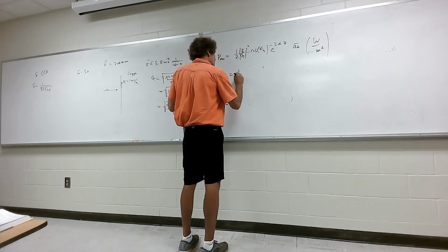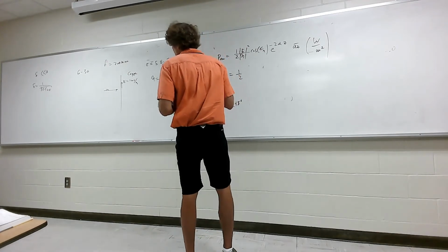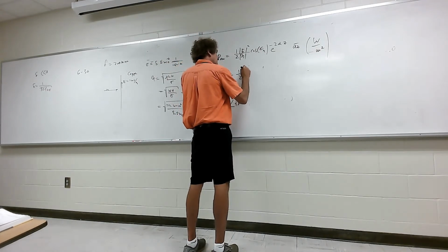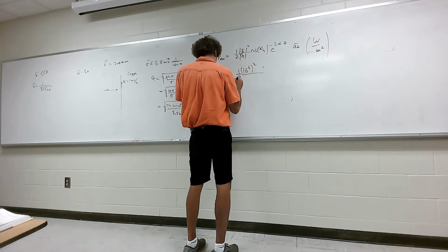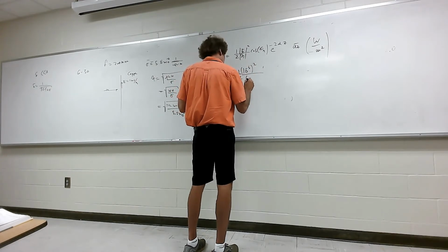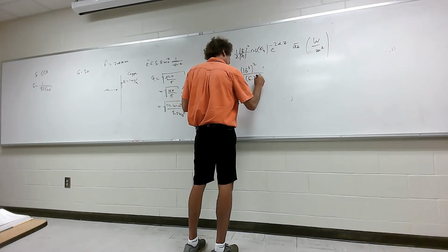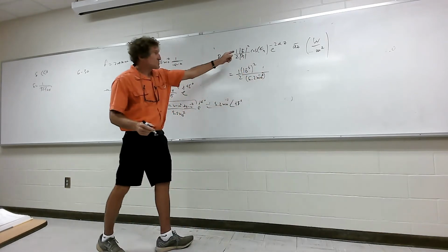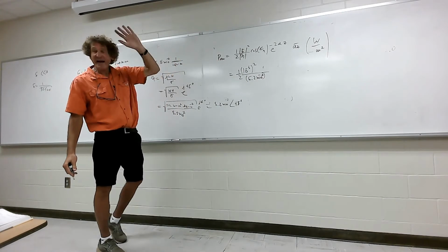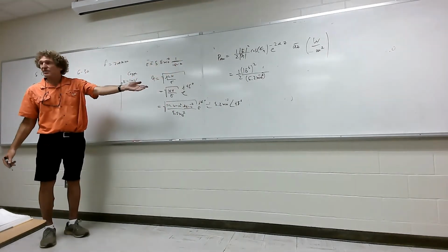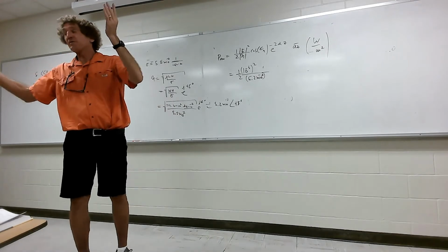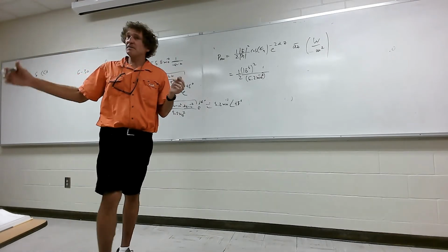It's 1/2 times the E field, given as a millivolt per meter, so 10 to the minus 3 squared, over eta, which is 5.2 times 10 to the minus 3. Now we have to get the cosine of 45 degrees, which is 1 over the square root of 2, or 0.707, about 70%.